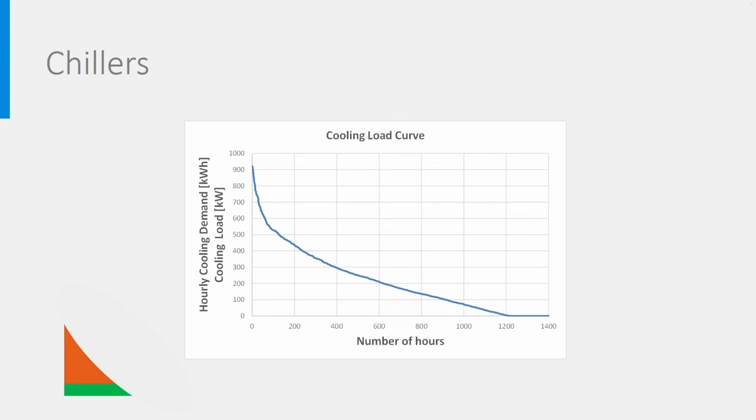So for chillers, either you do the full load and accept the price, or you do a bit less, like that, and just accept that for 5% of the hours it will be too warm in the building. This is mainly done in moderate climate countries and is sometimes referred to as top cooling, which is very confusing as it does not cool the top.